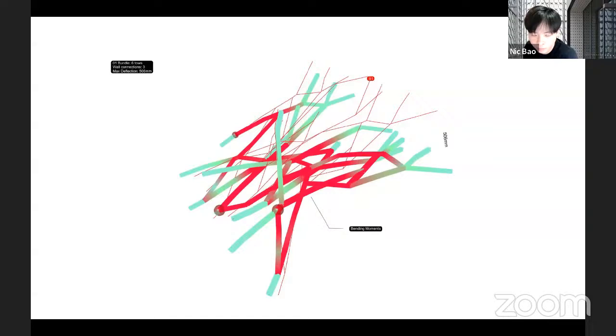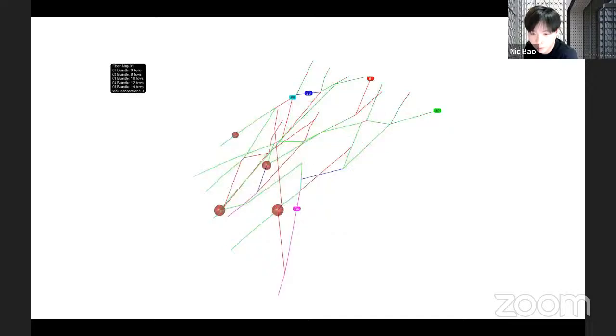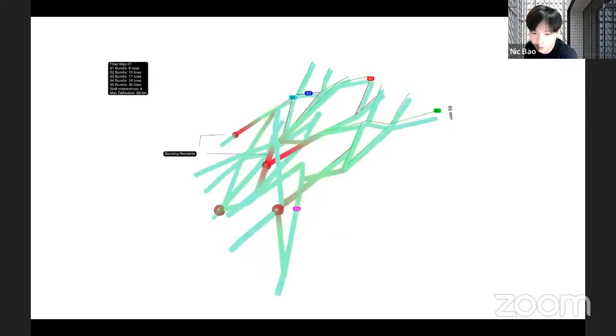The real-time structure feedback loop can help identify which part has more strength, then adjust the algorithm to figure out which part needs more fibers. After several iterations, you can see the reddest part is reduced, and it keeps the most efficient carbon fiber structure.